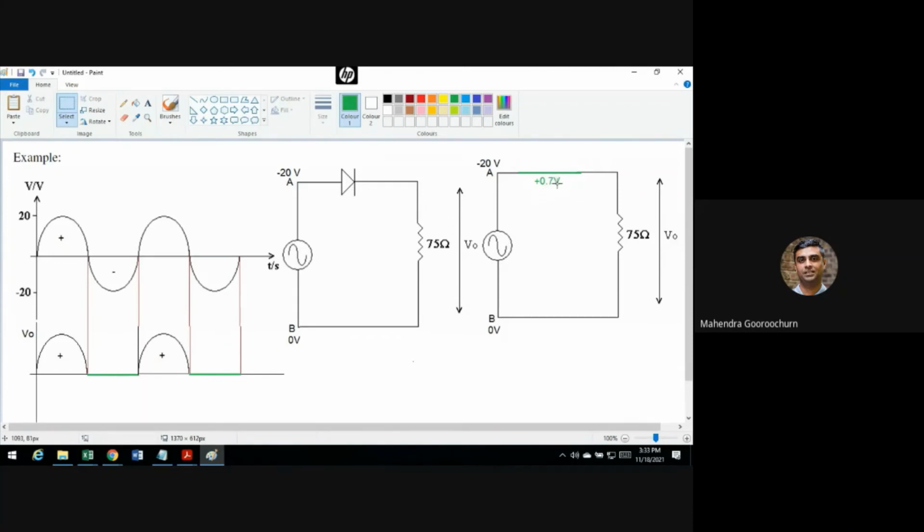So the fundamental difference between an ideal diode and a real diode is that 0.7 volts, which is required for a silicon diode for conduction to occur, and it's a drop which is always there when the diode is forward biased. In reverse bias mode, you will simply assume that it is exactly like this. So you will get 0. You have a very small leakage current that's in microampere, so that's not going to make a big difference. So this is going to still be like this. You might have a very slight difference, but that's not something you're going to worry about because the leakage current is in microampere, so that's not very important.